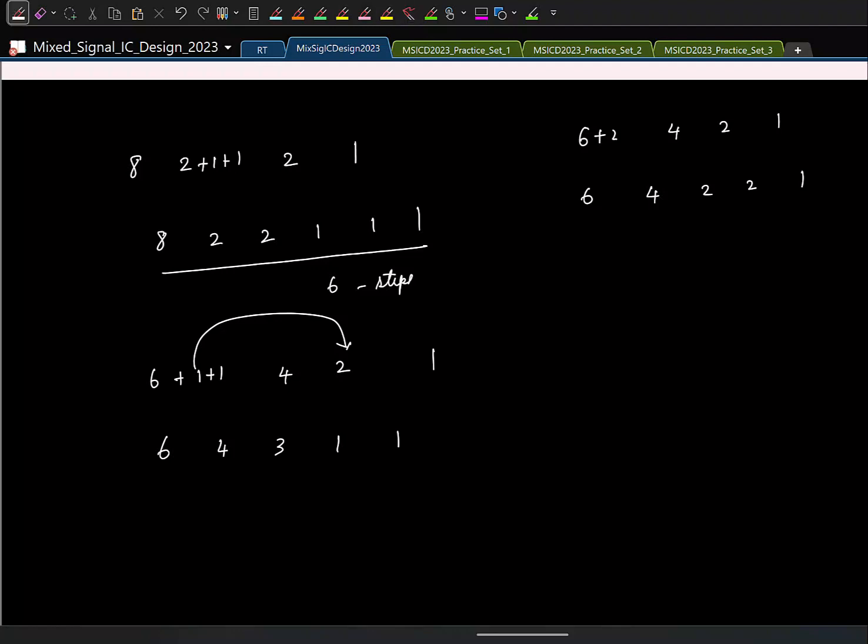And actually, if I have to put the timeline in perspective, as I mentioned before, this way of redundancy, wherein you keep the total number of capacitance, that is, we kept the total weight to be 15 and distributed this weight over multiple steps, is quite recent. It was introduced in 2015 by Liu. He's the same person who introduced this monotonic DAC switching.